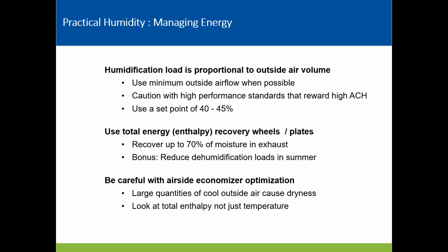The other thing that's quite common is using a set point down towards the lower range of the optimal, so 40 to 45% relative humidity. This is giving us a good margin of safety on the too high or too damp condition, while also minimizing the amount of moisture that needs to be added.